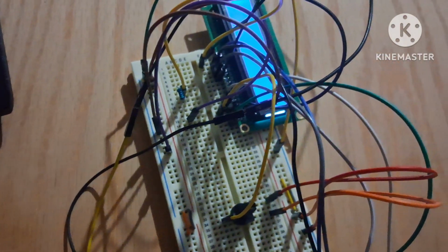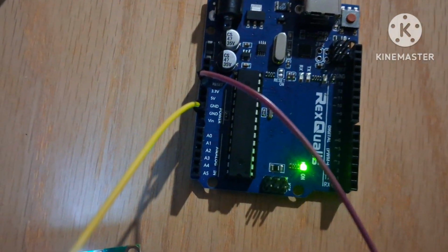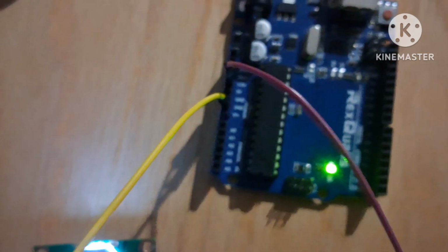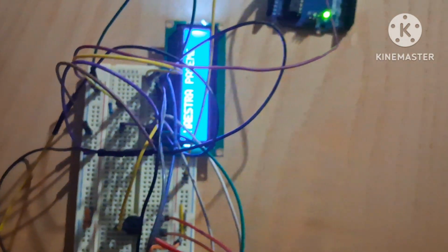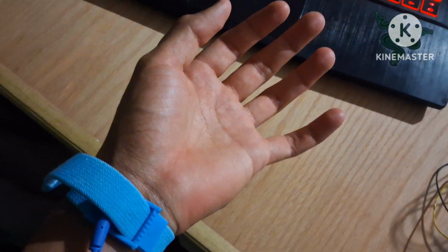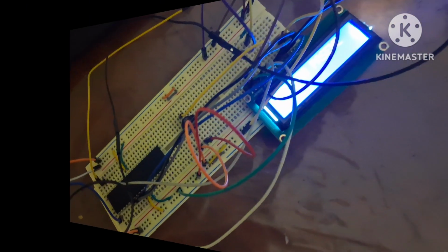It may also happen that we are not supplying the correct voltage to our circuit, and this can cause inefficient operation of the device. For example, in this case, we have connected 3.3 volts. Now we have 5 volts. In addition, the use of an anti-static bracelet is also recommended to avoid damage from electrostatic discharge.